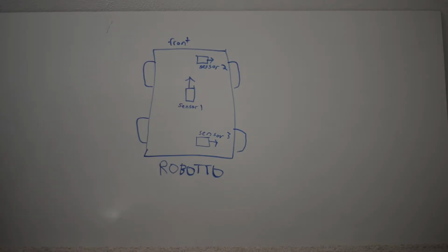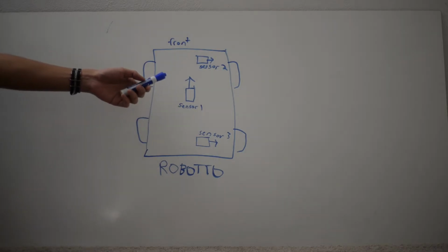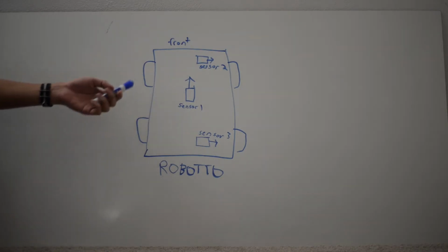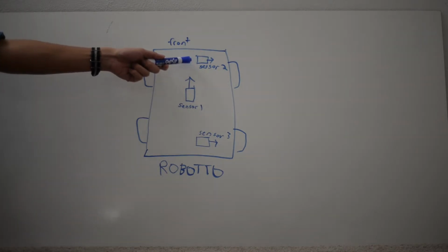As the sensor role, I was responsible for making sure the sensors were receiving valid and accurate data and sending that data to the master PIC in our message format. To accomplish this, I sampled 5 values from one of the sensors and sent the average of those values to the master PIC. Then I sampled 5 more values from this sensor and then sent that to the master PIC.